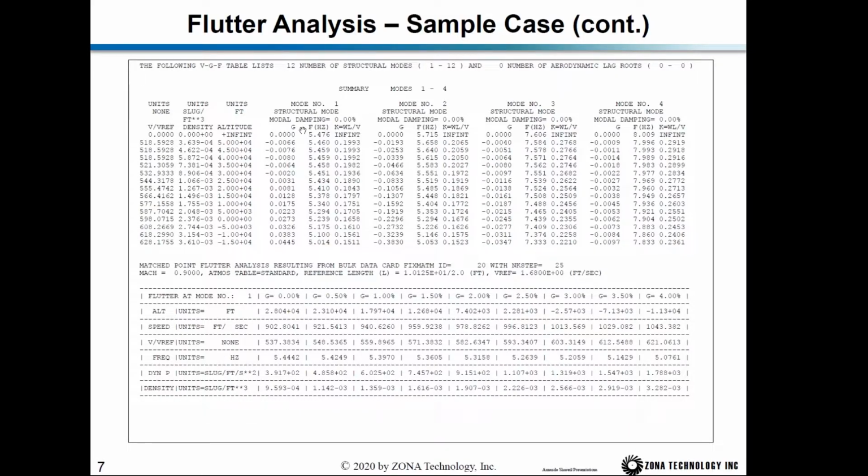So in addition to this modal damping specified by the TABDMP1 card, the flutter module will further add some structural damping from 0.5% to 4%. So if you have one additional structural damping, this is your flutter solution. And sometimes you will see this region is blank. Once you have a blank region here, that means if you add beyond 2.5%, there's no crossing.